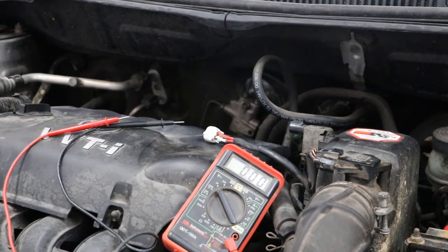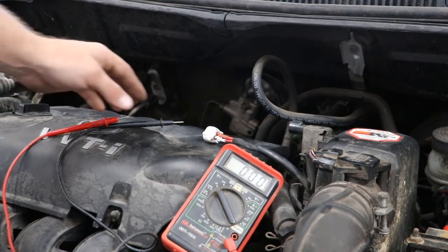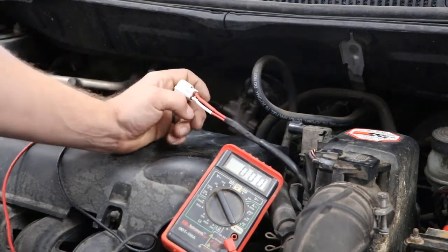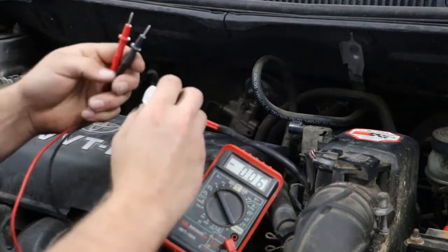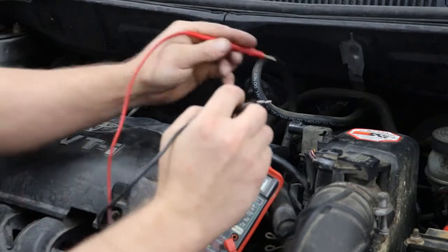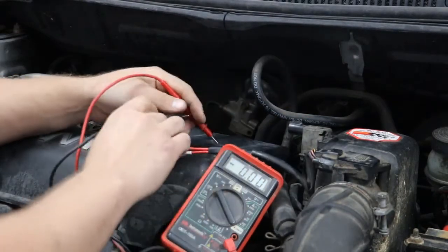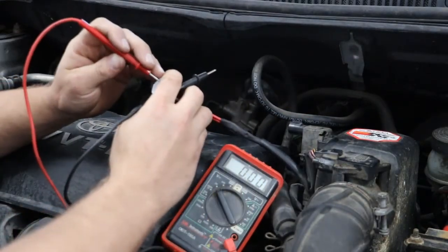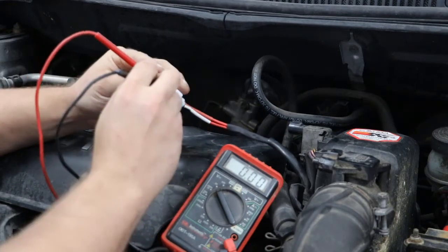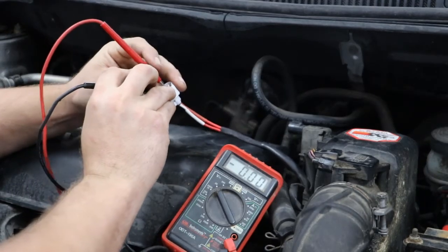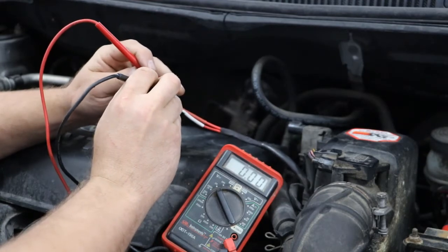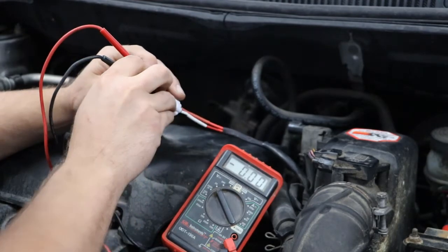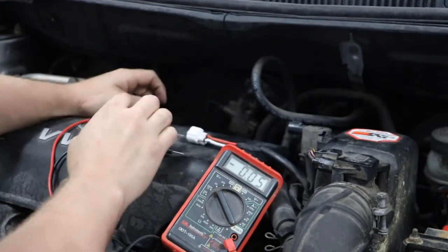Alright, so now we have our connector on, and the shrink wrap protects it from corrosion, water, all of that. What we're going to do now is test for the connection here to make sure we're getting positive power to the solenoid, and that's going to cause everything to work right. So we're going to stick our two ends into each side here, and right now it should show nothing, 0, as it's doing. Correct. Alright, so we have nothing there.